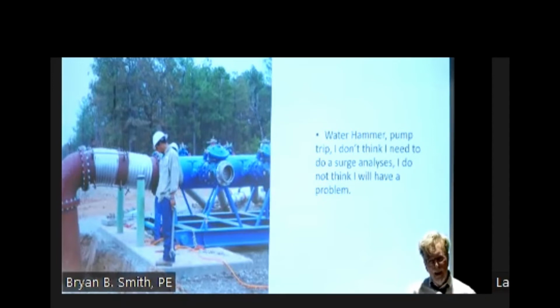So basically, what happens to water when it's exposed to a full vacuum? It starts to boil. So the negative wave goes out, hits the back of this 70,000-pound skid, blows out the back of it, and the wave reflects back. Remember, negative wave out, high pressure wave back, cavitation, implosion. They ripped apart their 24-inch piping, ripped apart the expansion joint, and blew apart their piping.